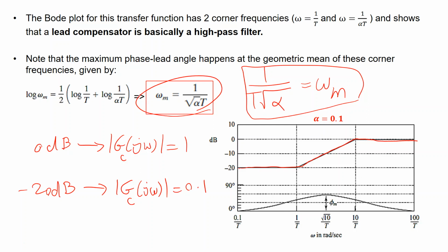Okay, so basically suppressing low frequencies while not suppressing high frequencies. That's why we call this a high-pass filter. And that is kind of similar to a derivative, a little better than derivative, a little more gentle than derivative, but that's the effect. It will amplify high frequencies. Noises are high frequency signals. So it is not doing anything with them, but low frequencies, whenever you want to pass a low frequency, it's gonna basically kill that low frequency. Okay, so this is the behavior of this